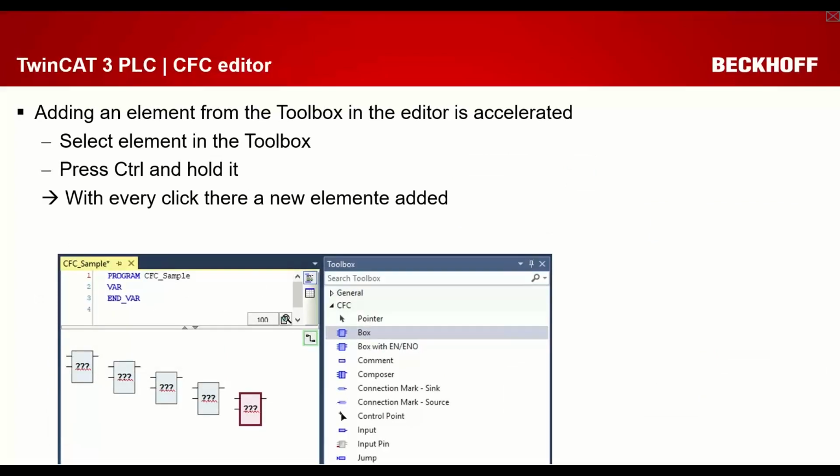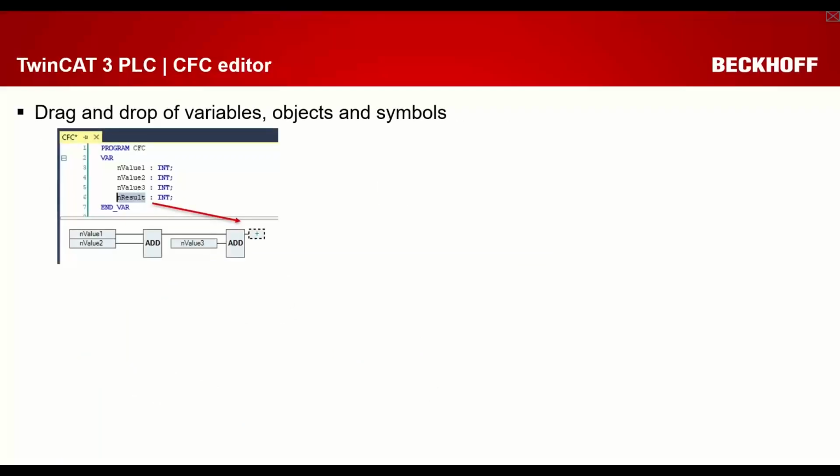And then we have added a new feature where you can increase the speed of adding new elements to the CFC editor. So if you drag and drop the box only once, this is of course still possible, but if you press the control button and hold it, you can also add this box multiple times at once.